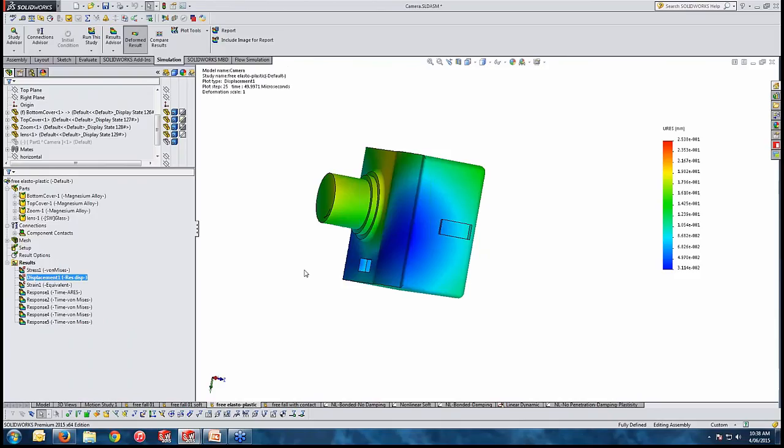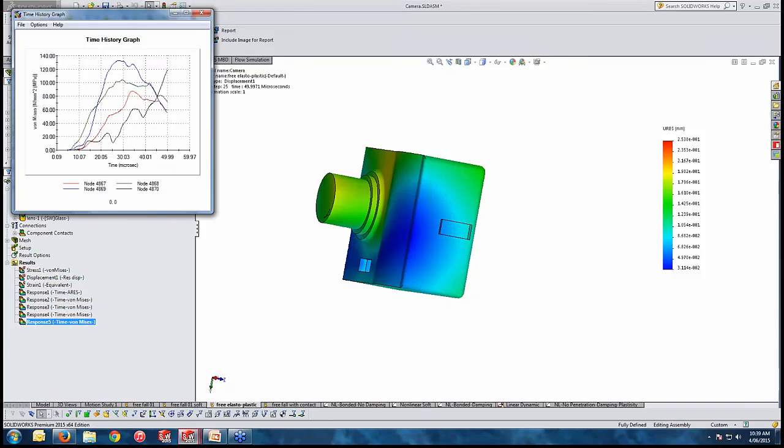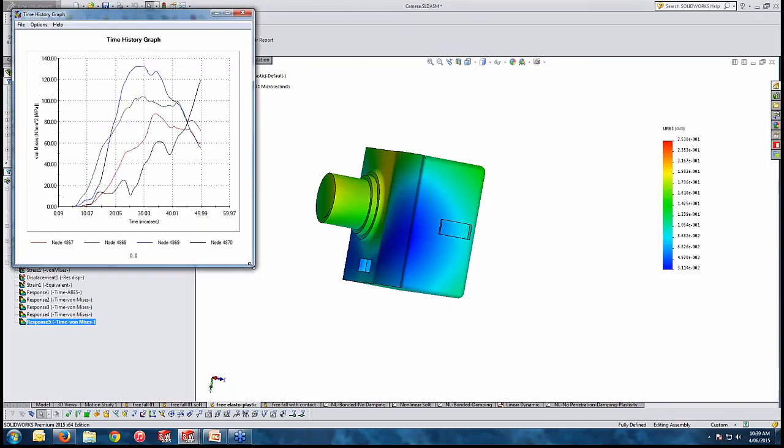Now we understood we are progressively reducing the top values of stress at the specific location we are looking at in a drop test when we are considering more and more reality, like there is not a super stiff target floor, or if we have, let's say, plasticity in our material.